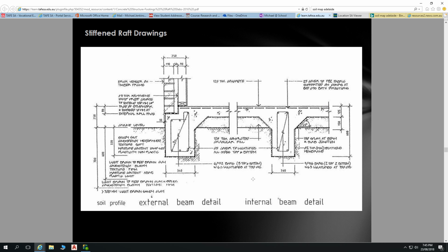So we have this detail in there for our concrete footings. And that may be a good detail for you to refer to. A little bit of funky stuff happening there with the measurements, though, in some things like beam widths of 260 and 340. I don't know anybody who has an excavator bucket of 260 or 340.